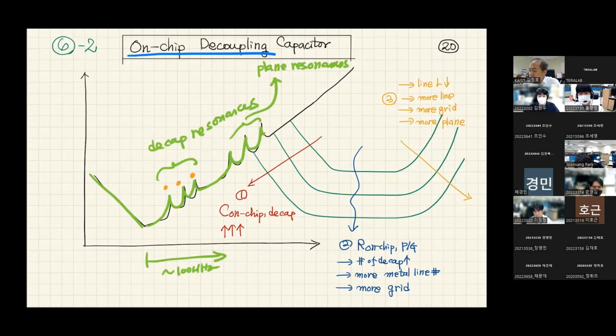It is coming from the wave properties of power supply current, because there is an incident wave and a reflected wave, and by combining that, we're gonna have a standing wave, and because of that, we are also having resonances, and we are going to talk about that in a little more detail later in this month. Usually it is coming from PCB plane designs, and it is coming from decap designs.